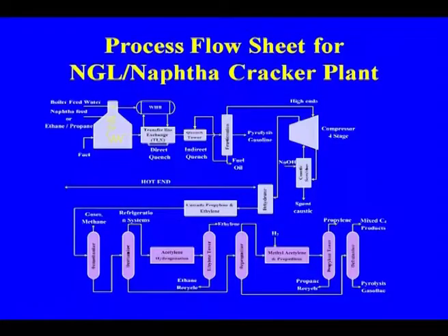temperature. This is actually the complete cracker plant, where after the cracking there is the naphtha, and here also the ethane, propane. This part will be only after the separation of ethane, propane from the natural gas, and fuel oil that we are adding. After the cracking comes the transfer line exchanger, where steam generation is there, the indirect quenching, then direct quenching, and then after the compression and the removal of impurities, we are using the NaOH scrubbing. So, spent caustic will be there, and after that the removal of impurities, CO2 or H2S, it will go to the separation, where the demethanizer is there, and in the demethanizer we are separating methane.